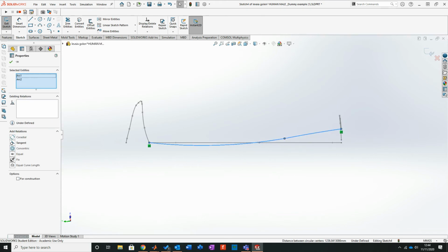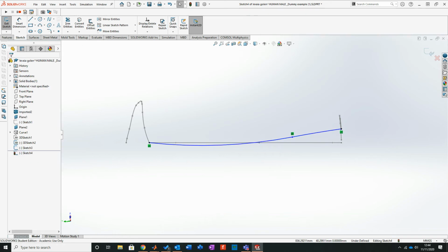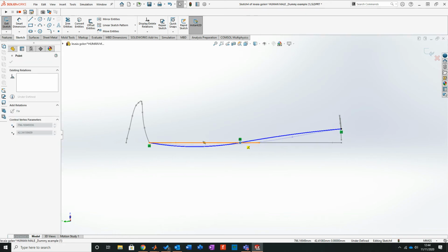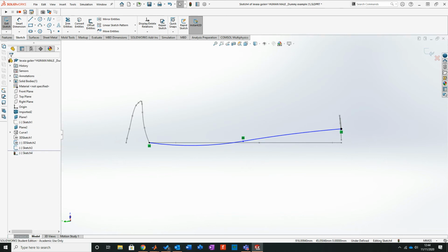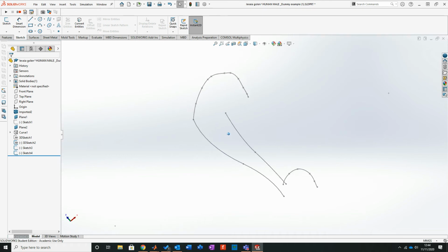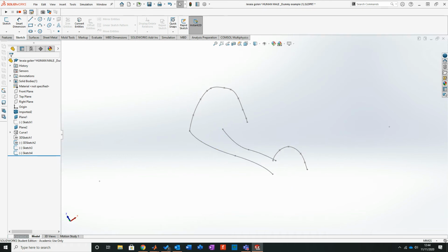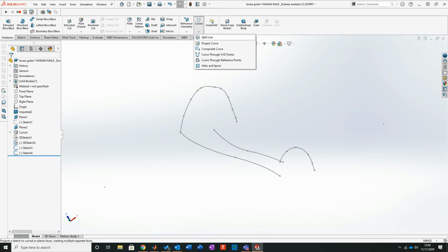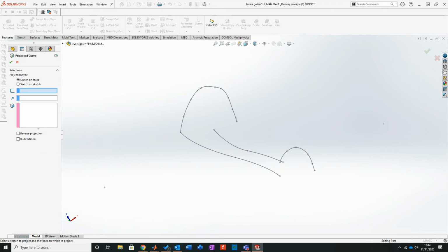And so I do like a good curve. Because I can't see that side profile of the shin guard, I'm actually just adding a curve in there just because I'm being bold. So now we've got these two profiles. I need to create the all important guide curve. So all I'll do is go features, curves, project a curve between sketches, you and you.